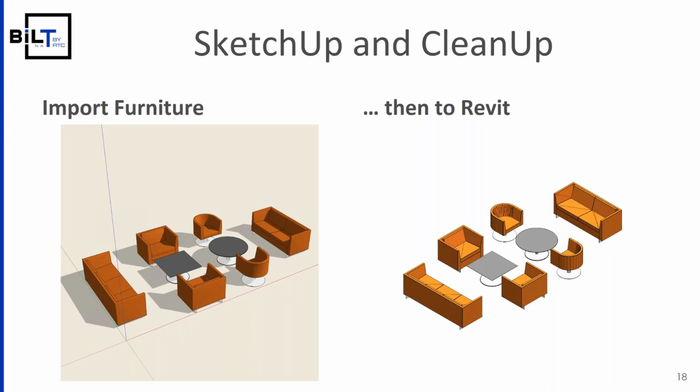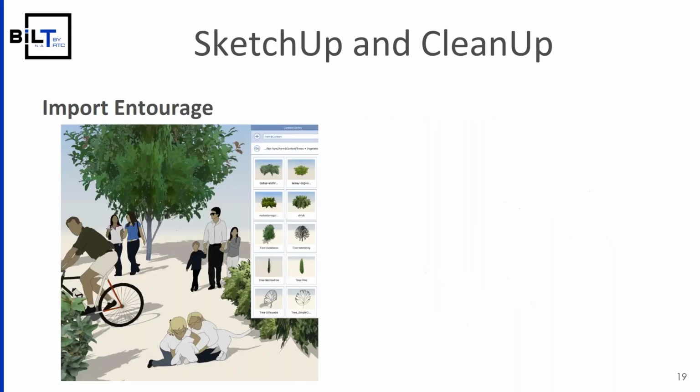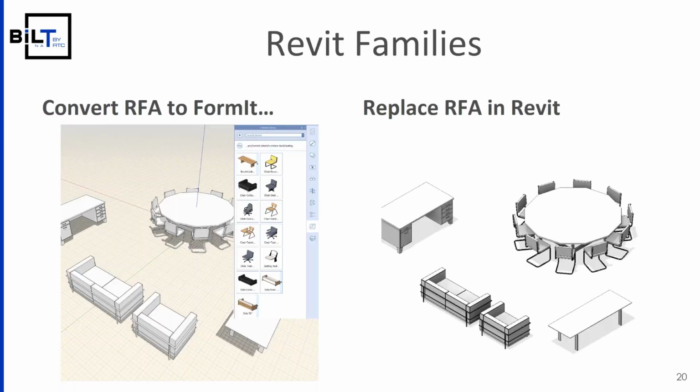You get these kind of nasty facets on them. I think you can see those. Nothing we can do about that. They are real facets in the geometry, so Revit displays those. But what's nice is if you go into the realistic render or the ray trace rendering in Revit, or the live VR experience or live rendering or other rendering tools that are in Revit, those edges will disappear. So you can start to do VR and other high fidelity presentations very quickly with this content if that's what you needed to generate and you needed to pull it off of a design model. So pretty handy.